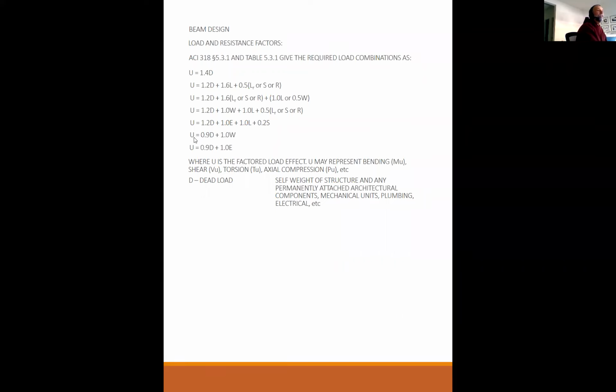So you will notice that there is no load combination that has earthquake or wind in the same combination. That's just unreasonably improbable to even include those two in the same combination. What is the likelihood that you have too many people on the same day as a windstorm? So we decided to let 800,000 people onto the Golden Gate Bridge. Oh, and by the way, we got a hurricane coming in from Hawaii.